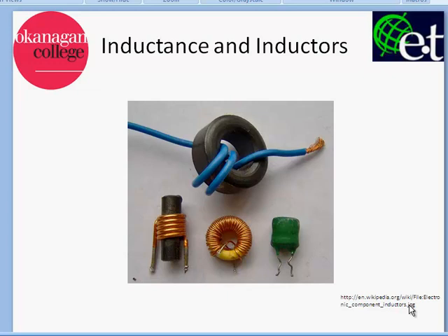Well, it turns out that the single current carrying wire will induce a voltage across itself that's going to create an opposing current to create a magnetic field that opposes the changing magnetic field caused by the original changing current. Now, this is kind of a crazy concept. We have these two complementary effects of electromagnetism and electromagnetic induction that are manifesting themselves simultaneously in the same wire coil, and this effect is called self-induction. And it's really not as complicated as it seems.